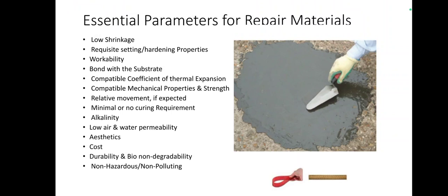Substrate means the old concrete, and the repair material should have a compatible coefficient of thermal expansion. Whatever expansion happens for the concrete, similarly it should also expand. If there's a difference in expansion, it will result in stress concentration and cracks will be formed. And it should have compatible mechanical properties and strength.